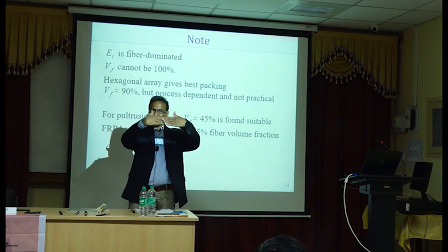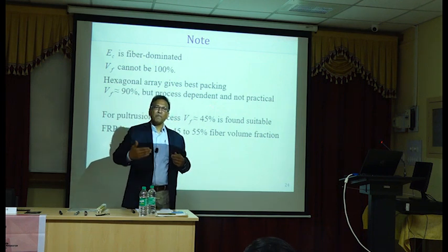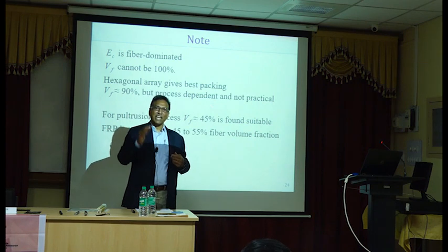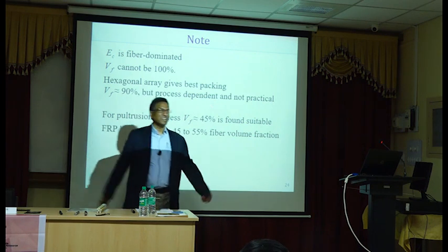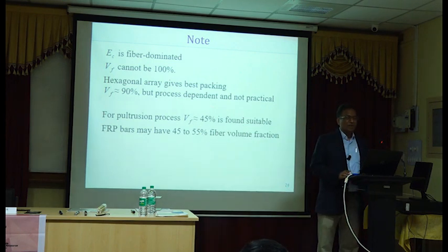The main thing is the load transfer. There has to be load transfer between fibers. And if there is no wetting, there is no load transfer. If there is no load transfer, the composite will fail. Okay, thank you. That's the number one purpose of the matrix.